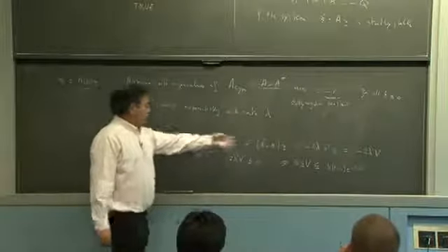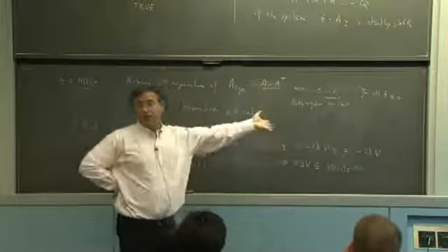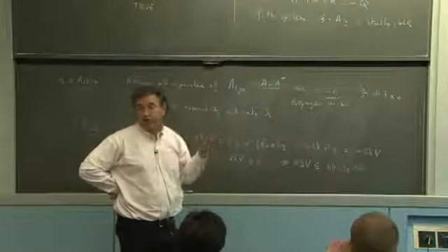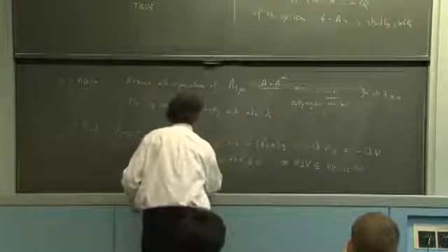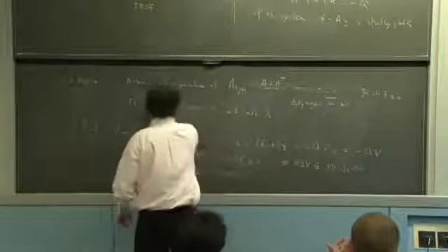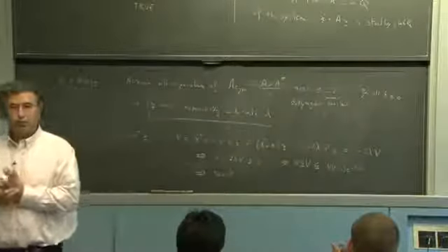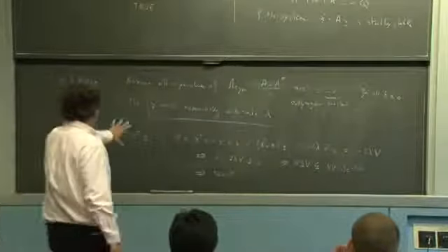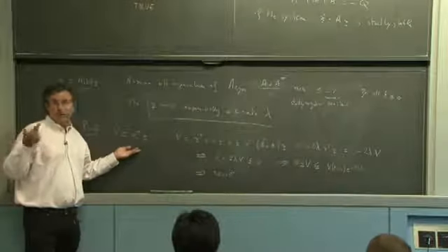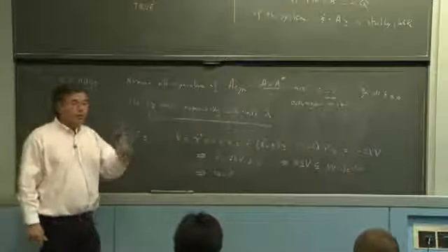And therefore, V, remember, is the norm of x squared. So it says that V converges to 0 with a rate of 2 lambda, so x converges to 0 with a rate of lambda, which means the result. In other words, we haven't used the Lyapunov theorem or an invariant set theorem, anyway we're dealing with a non-autonomous system. But we've fundamentally used Lyapunov ideas.